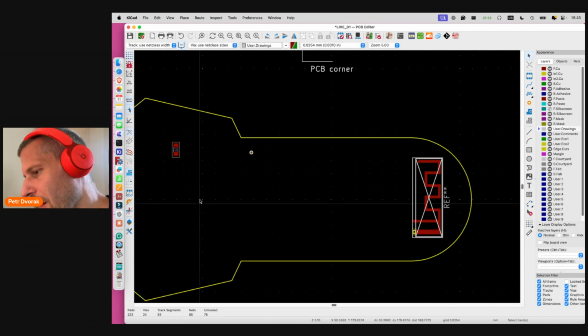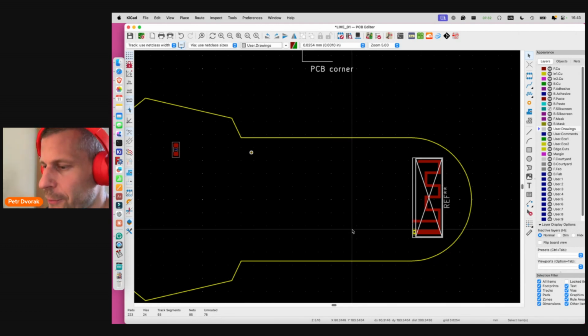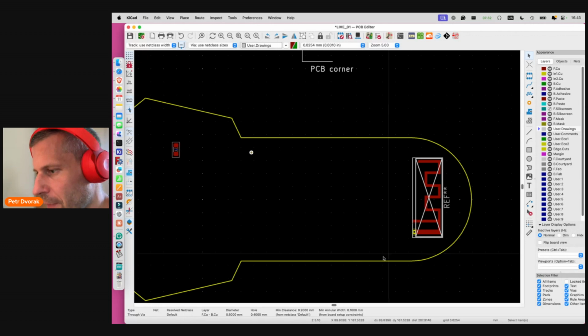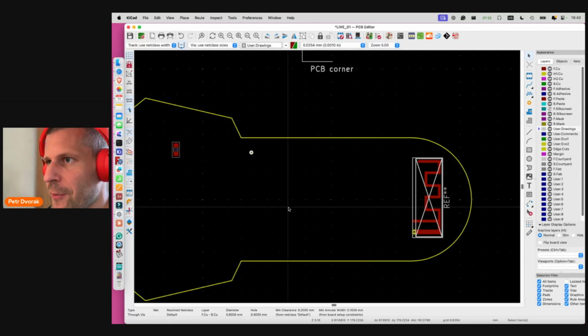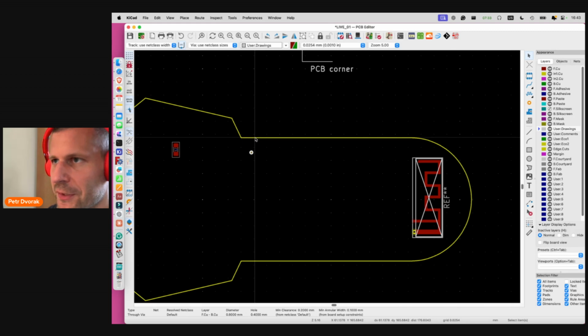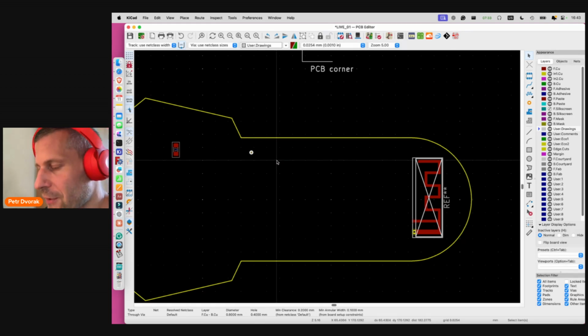And let's say that the entire part of the PCB will be covered by the copper plane, grounded, connected to ground. And you need to place the stitching vias there, and the entire area must be filled with the stitching vias, and you want to deliver the nice looking job, so you need to place the vias in the grid, not zigzag, but in the grid, because it's pleasant to look at a well driven and well drawn and well designed PCB.